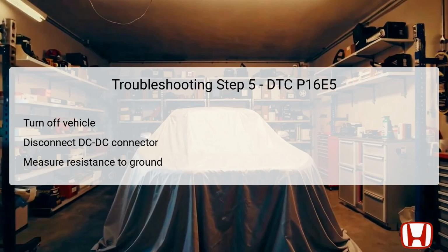Now, to assess potential causes, turn the vehicle to off or lock mode and disconnect the DC-DC converter connector A, which has 3 pins. This step is crucial for checking the integrity of the communication circuit.